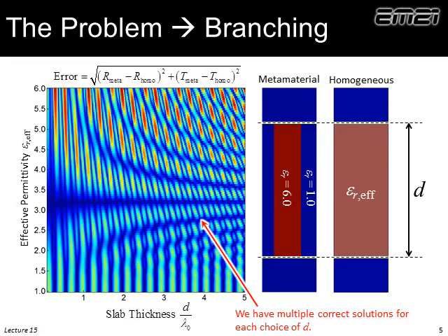Here is what I think is a good example of the troubles that we encounter. So bring your eyes to this middle diagram right now. What we have is a finite difference frequency domain simulation of a subwavelength grating. So we're looking at the cross section of the grating. Here's one tooth. It has a dielectric constant of 6, and then it has air gaps between the teeth. And of course there's air on the top and the bottom. So the question is, given this slab of thickness D, what are the effective material properties of that? If we do that correctly, we should be able to replace our grating with a homogeneous slab with this effective dielectric constant, same thickness, and then we would see the same transmission and reflection.